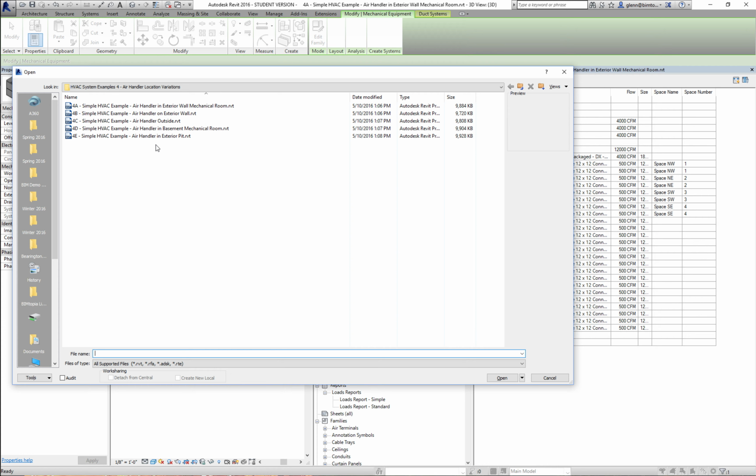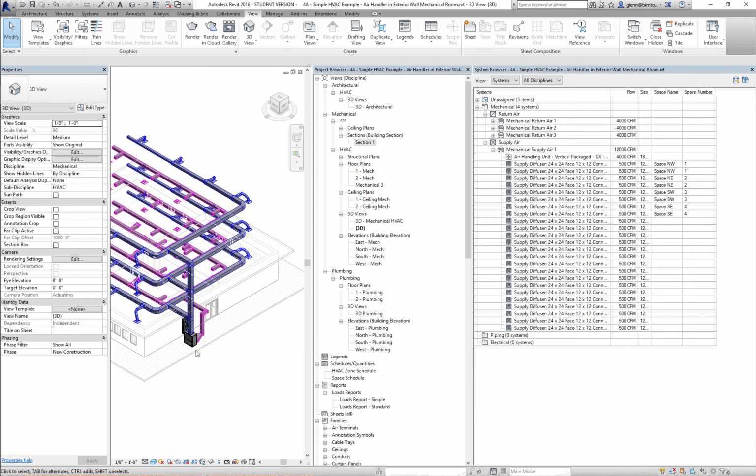If you have a mechanical room on an outside wall, we can put vents right in the wall of the mechanical room. If you have a mechanical room on the inside, we may have to run a return air duct up through to the roof or something like that, to either exhaust the air or bring fresh air in to the air handler. Here, I just put it outside. So it all starts with these air handlers.